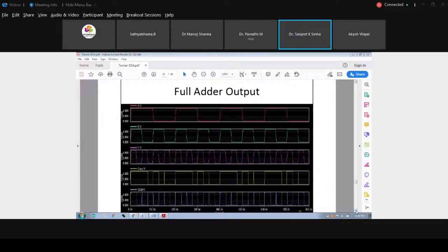Transmission gate is simply a combination of NMOS and PMOS, and it is easier to design. If you go for the transmission gate implementation of a multiplexer, then it requires the minimum number of transistors compared to implementing it by using the basic gates. You can see we are having 4 3-input AND gates, 2 NOT gates, and 1 4-input OR gate. So it is quite complex. That's why we will use this 4:1 multiplexer.